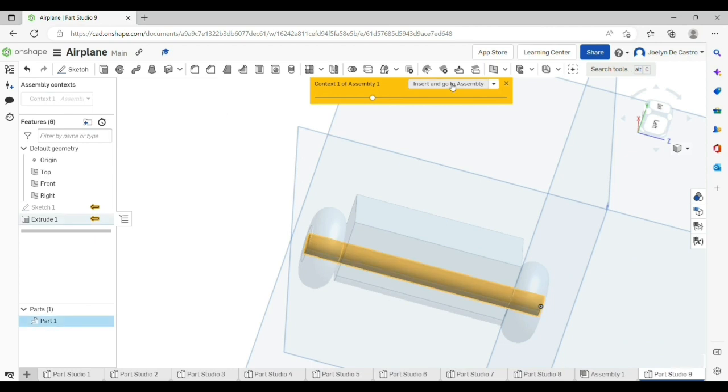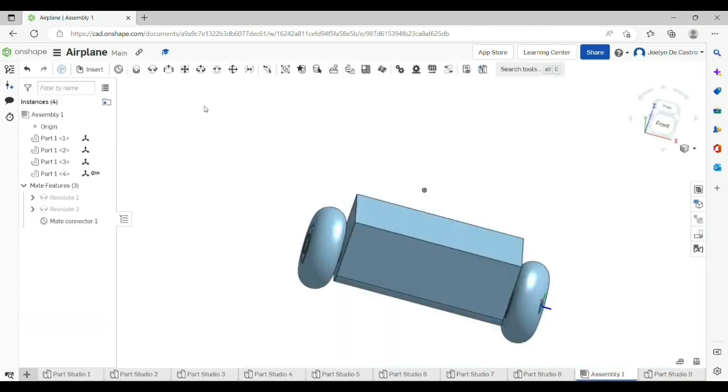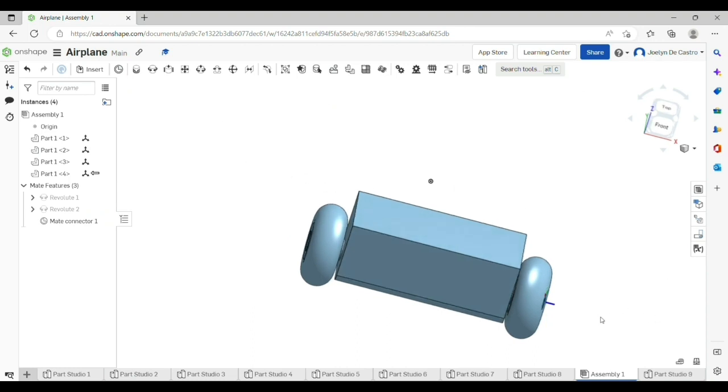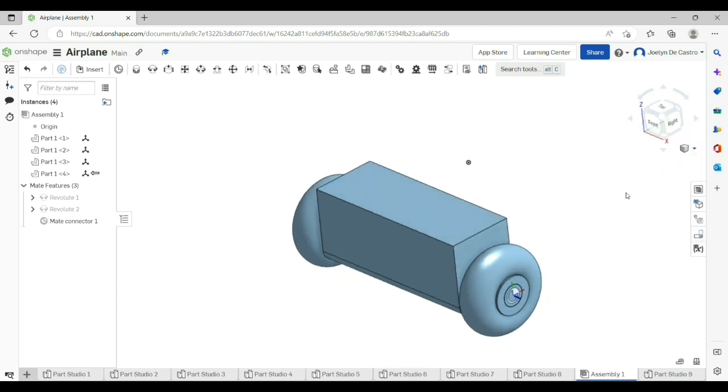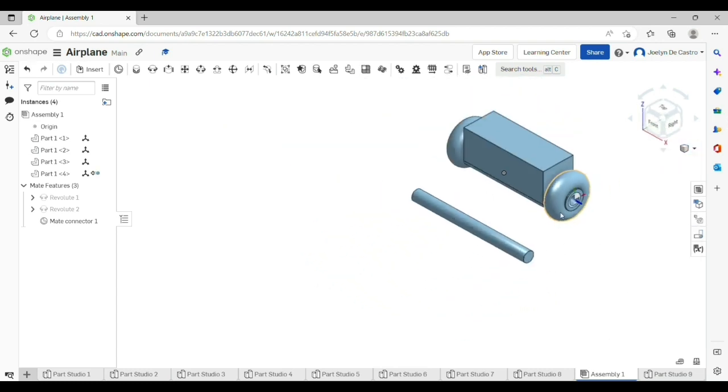I can see the parts in my assembly and use information from those when I'm creating this part. In this case, start a new sketch and click the end of this wheel. Right-click and view normal to the sketch plane. I'll use my use command on this hole that was in the wheel for the axle to define the axle. Accept this sketch, then go to the isometric view.